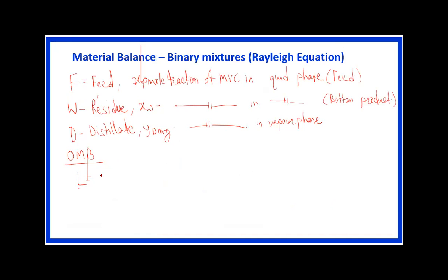L equal to L minus dl plus dd. So L is the liquid, that is in terms of kilomole of the liquid left in the still, and dl is the small element of liquid, and D is the distillate, and small dd is the small element of that distillate which is vaporized or condensed. So input is equal to output. In the same way, we can write L equal to L minus dl plus dd. So if you observe this, dl equal to dd, because this L and L will cancel.